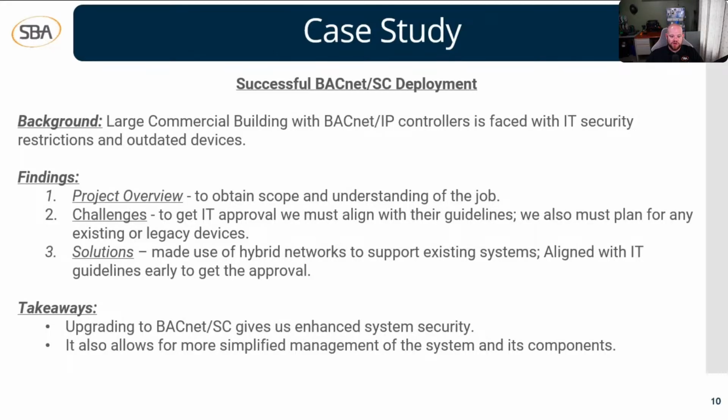The second thing is that we must also plan for any existing or legacy devices. Let's say in this instance they said you have 20 controllers in the building and 5 of them are outdated and they're security concerns. We need you to either upgrade them, take them out, whatever you have to do, but they're a mega security risk. So if those 5 devices they said were bad are the 5 we're replacing, but these other ones are okay, and they're probably still BACnet over IP or MSTP devices, but they're fine. They're not a security risk, so those stay.